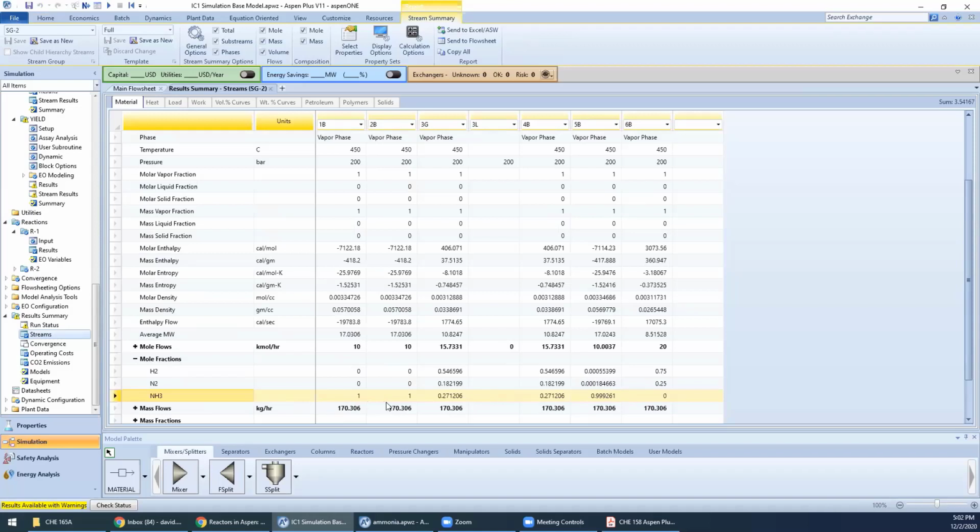Is it lower than all of these? 15 to 25%. Yeah, I was actually going to say 21%. So yep, that's right in there. A single pass through an ammonia reactor is that low, which is why you have to recycle it at least 7 or 8 times. Each fluid element as it goes through, you have to recycle it that many times.